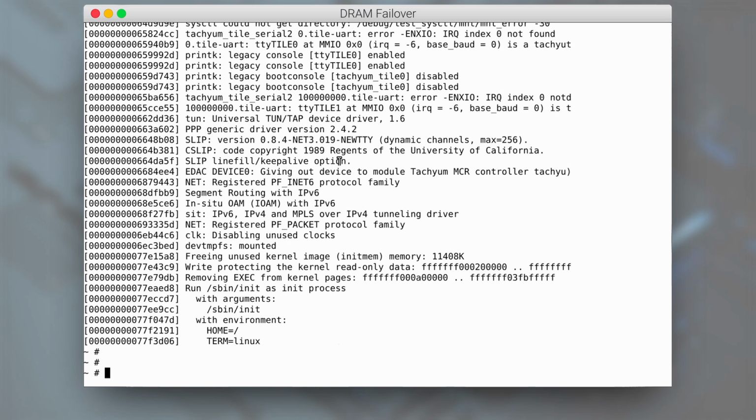At this point, we're using them to monitor four aspects of the memory subsystem: the number of accesses to the particular DRAM subsystem we're looking at, the total number of DRAM ECC errors that are detected on those accesses, measured in 8-bit symbols, the number of times we encounter two errors in one word, the double error case, and the number of triple errors that are encountered in a single read operation.